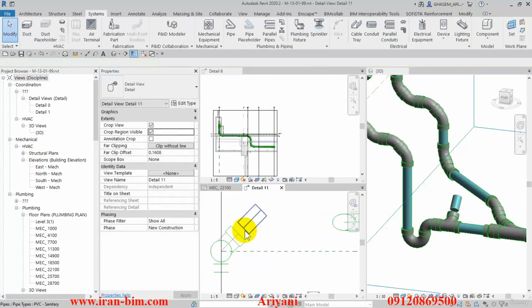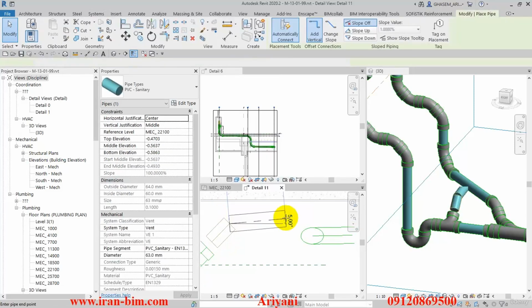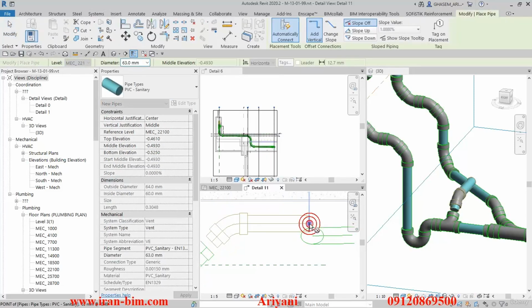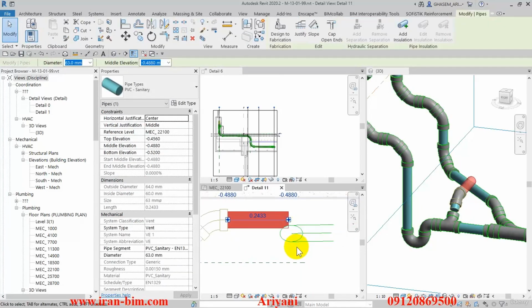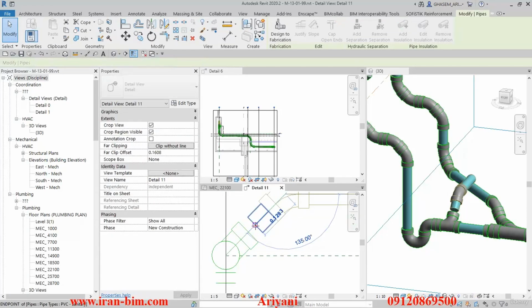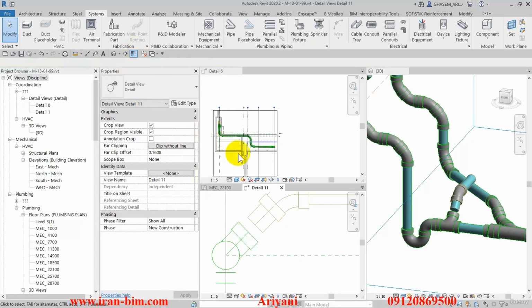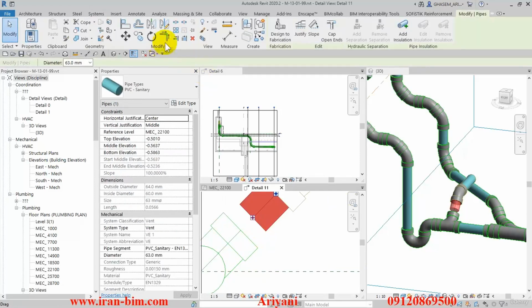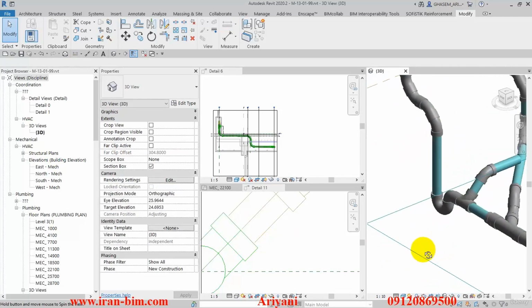Alright, then I can right click on it and select the draw pipe option once again, and then I can connect it to this side. Now I'll select this and move it on top of the pipe on the right so we won't have any collision points. Alright, now from the left side I'll connect it to the pipe system, cancel on this. So once again select the align tool and lock this up with here, and then using the trim tool we'll connect these up as such.